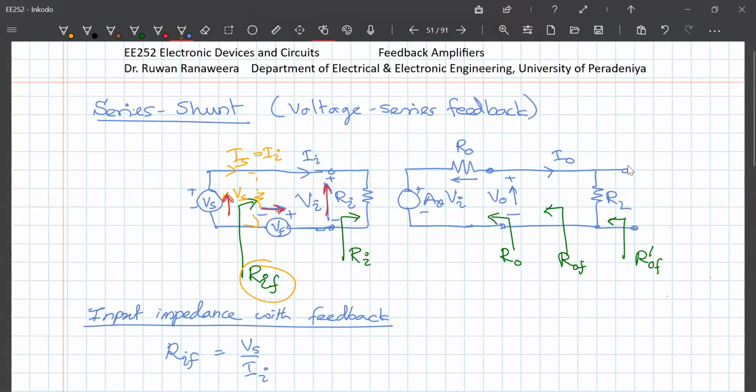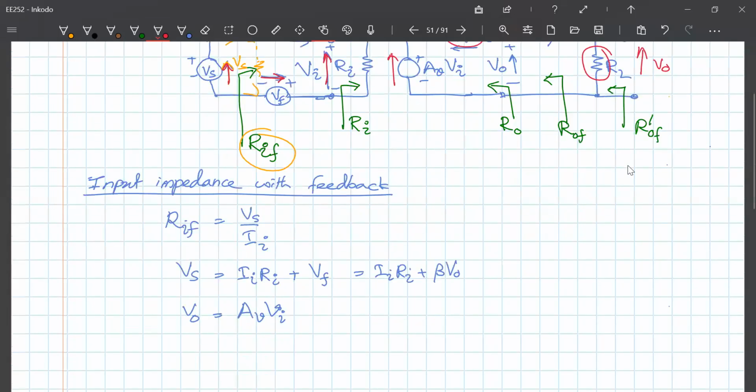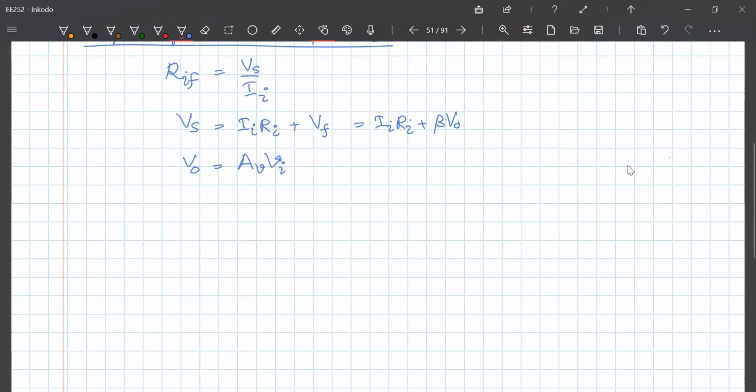times. Now I can look at it as a voltage division. So this is the only voltage source that I have, and that voltage, the output voltage V out, so this is the V out here, will be the voltage division between this resistor and this resistor. Okay, so therefore I'm going to write V out as RL divided by RL plus R out. Okay, hope this is clear.